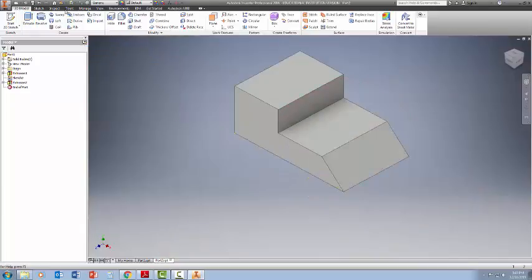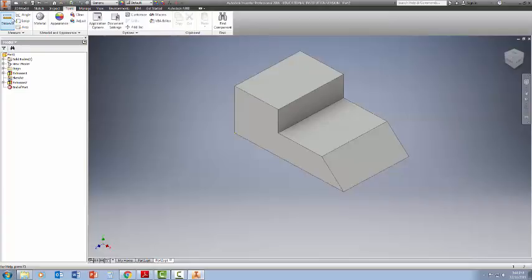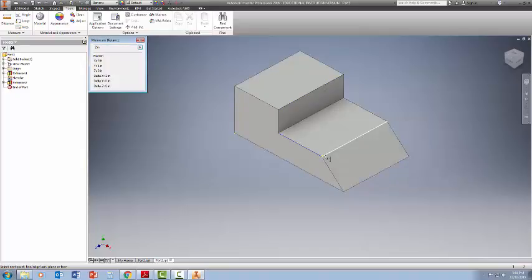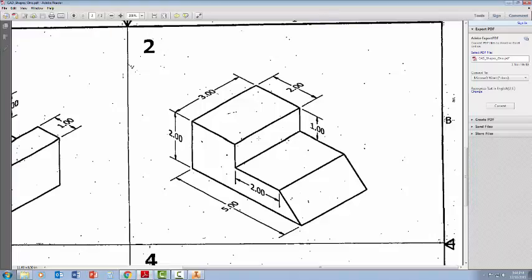Enter. If you don't know how big something is, or if you think you made a mistake, come up here to the top where it says Tools, click on Tools, and click on Distance. And you can grab corners, and it'll tell you that's 3, here to here, that's 2, here to here, right there, that's 1, and it matches, 1 inch, 2 inch, 2 inch. Okay, it'll match what you have on here. Alright, and that's the first 2 objects done.